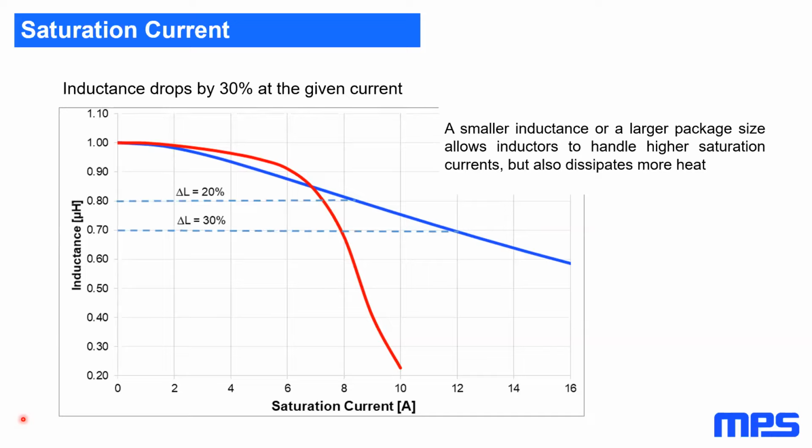And for every MPS inductor, we are able to have an MPS inductor selected, meaning we have a wide range of inductance values that are matching with the MPS inductors as well. And we have also an inductor calculator tool on the website. When you are selecting the IC and you know your converter specifications, what are the inputs, the outputs, what frequency, what ripple current, you just need to put this information in the inductor calculator tool, and this will filter according to this selection. And also, I have to mention that MPS inductors have right now a lead time of about 20 weeks.